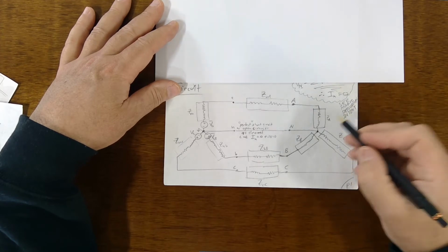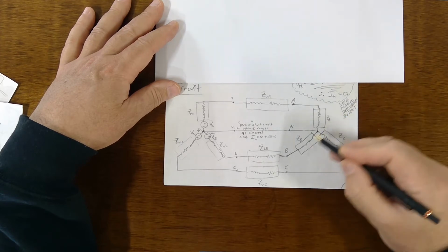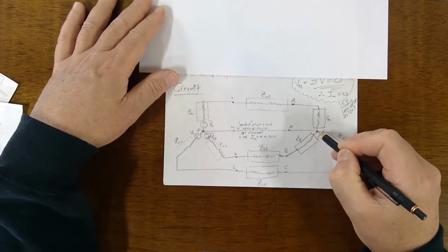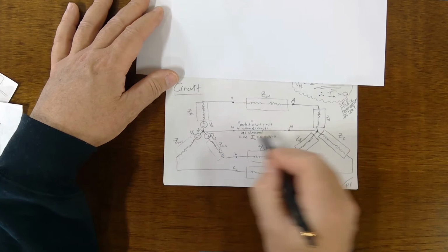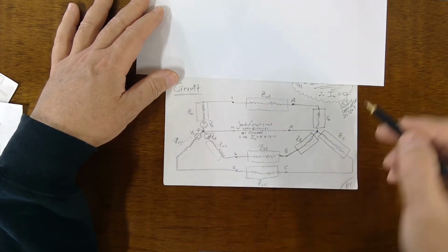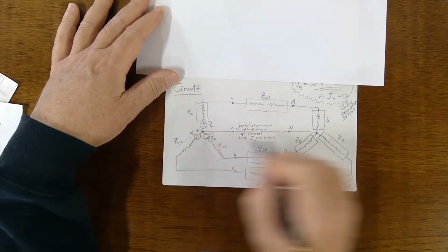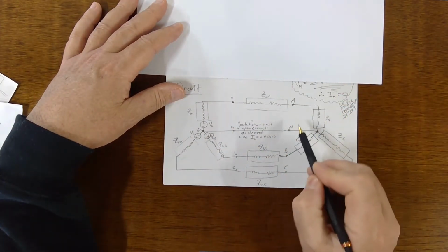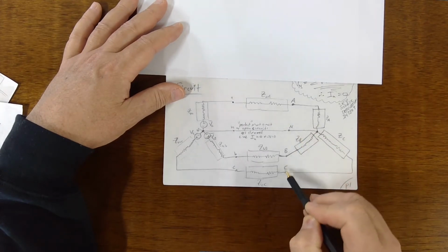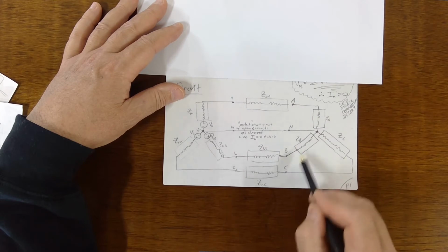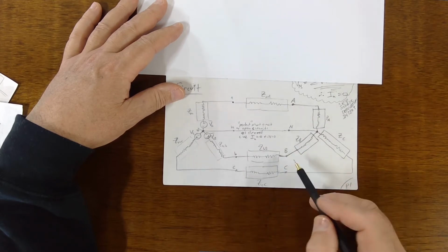That's what we mean by balanced, is the impedance of each one of these is the same. If that's the case, then the voltage at this terminal will be 0. The current in here will be 0 because the current will be going back these other ways, and because the voltage potential is 0. So the currents in each of these other lines, the current in here, the current in here, the current in here, they're all going to be the same.